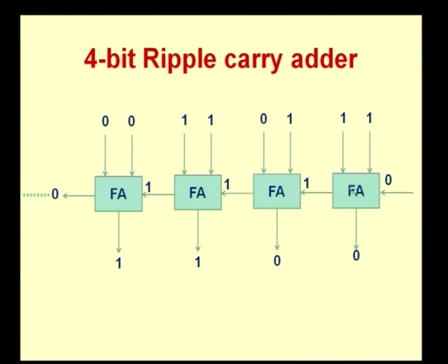Okay. This is what we have in a 4 bit ripple carry adder. We will look at how to address this delay a little later, but right now you understand that this is a simple adder that is constructed with n number of full adders. Okay. Now, you can extend this further. So, now we said a 4 bit adder can be constructed like this, a 32 bit adder can be constructed like this, and so on.